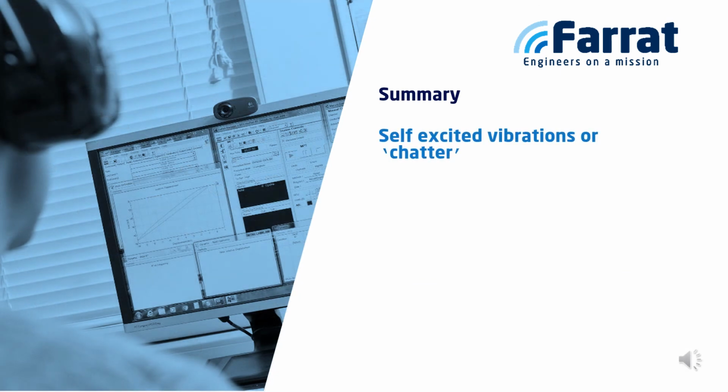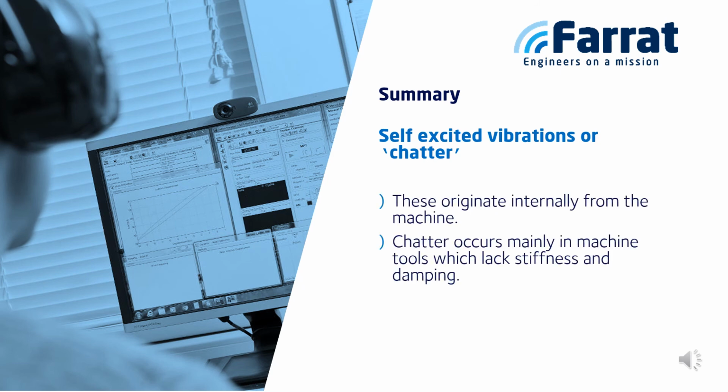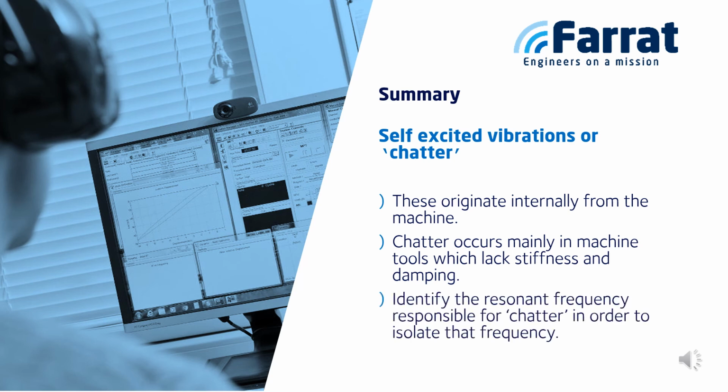Self-excited chatter vibrations originate internally from the machine. Chatter usually occurs in machine tools which lack stiffness and damping. In order to resolve chatter, you will need to identify the resonant frequency responsible using tools such as modal analysis.